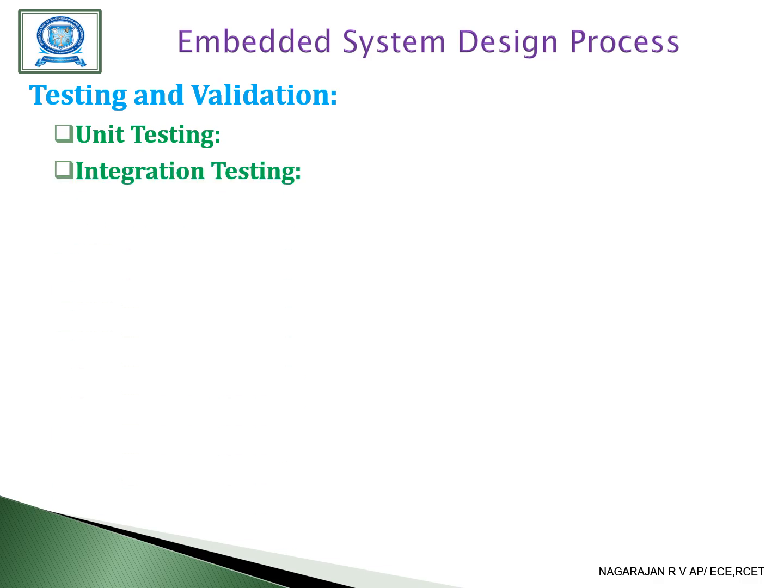The next testing is integration testing. The system is assembled and the integration between the different components is tested to ensure they work together as intended. Testing scenarios often include system-level functionality, real-time performance and communication between modules. The next one is validation and verification. Validation ensures the system meets the user needs and operates correctly in its intended environment. Verification confirms that the system meets its specification and requirements, often involving formal methods or simulation to prove correctness.